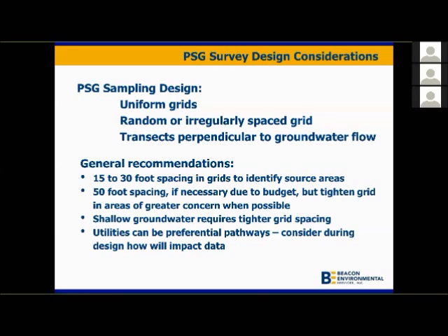When we're tracking contamination in groundwater, we put samplers out in transects, and we've tracked groundwater contamination at depths greater than 75 feet. With this approach, we recommend having the samplers in spacing of 25 to 100 foot between samples within the transect.